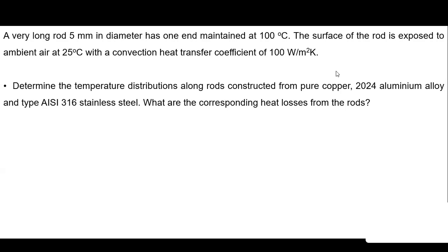What we have to find out? Determine the temperature distribution along the rod constructed from pure copper, 2024 aluminum alloy, and type AISI 316 stainless steel.